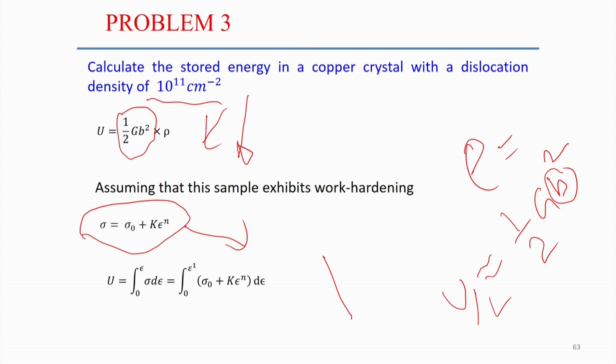If we completely define the stress strain curve, suppose this is the point, at this point the strain is equal to E1, for example, and the stress is sigma. At this specific point the stress we reach is from the base stress sigma 0, and the remaining part comes through the work hardening mechanism, through which the strength increases up to that point. So at that point sigma is given.